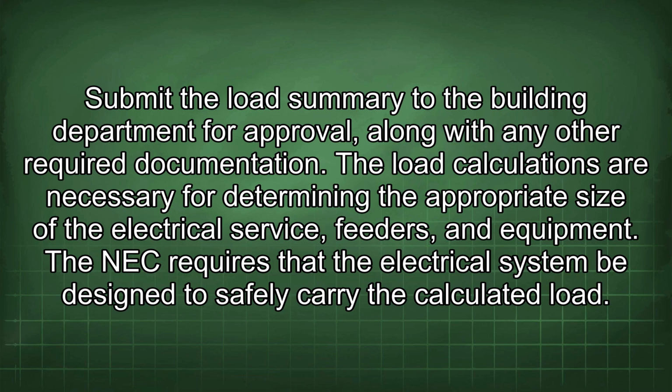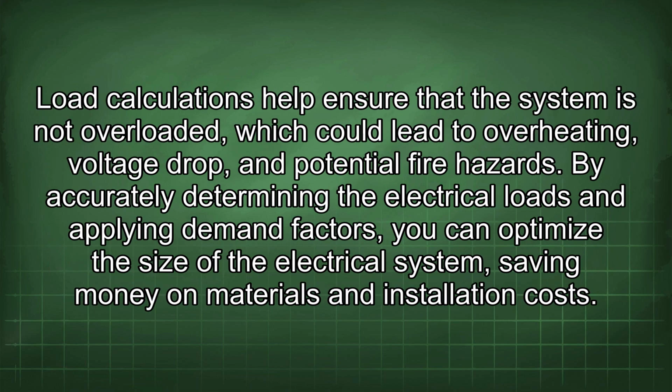The load calculations are necessary for determining the appropriate size of the electrical service, feeders, and equipment. The NEC requires that the electrical system be designed to safely carry the calculated load. Load calculations help ensure that the system is not overloaded, which could lead to overheating, voltage drop, and potential fire hazards. By accurately determining the electrical loads and applying demand factors, you can optimize the size of the electrical system, saving money on materials and installation costs.